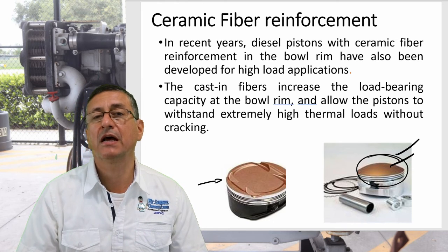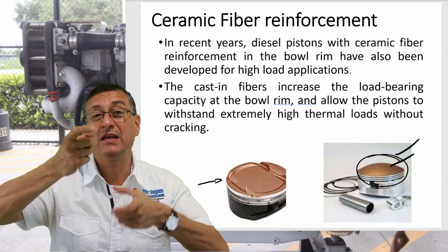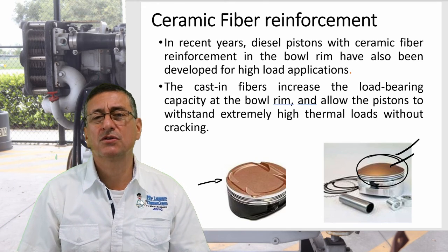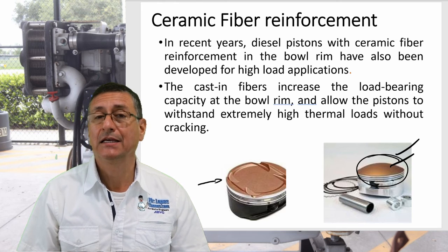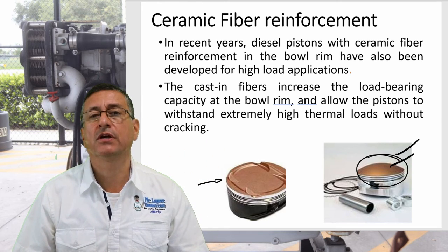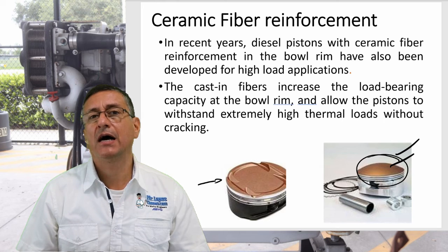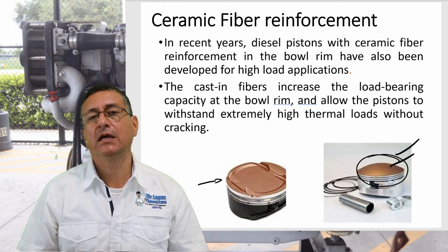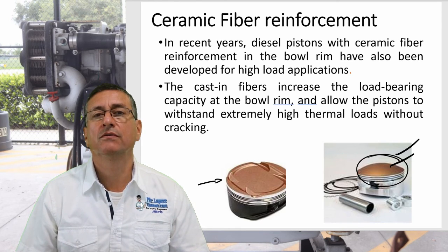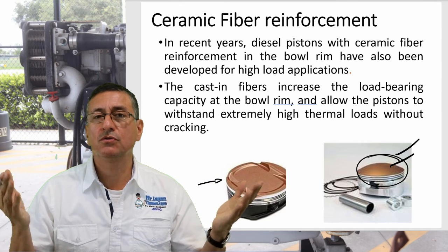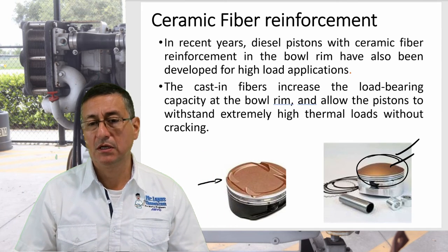Those pieces of ceramic are in movement inside of the combustion chamber and destroy the face of the valves, destroy the head, and produce catastrophic consequences. I don't recommend adding ceramics on the head of the piston because the temperature of diesel engines destroys sooner or later those ceramic coatings, and you introduce catastrophic consequences in the engine.